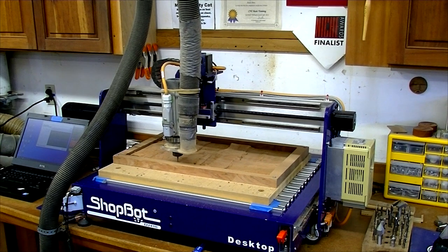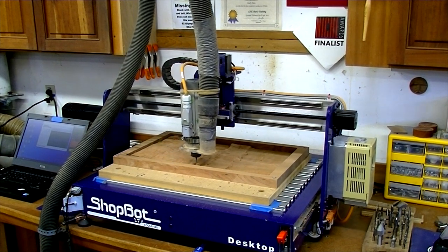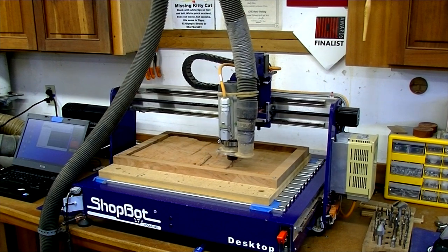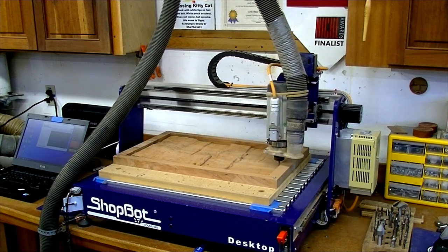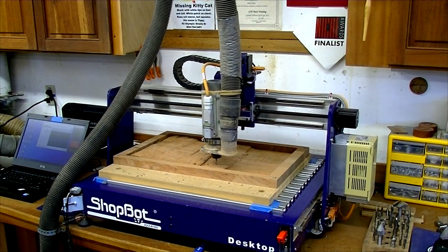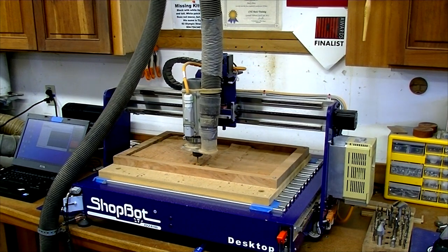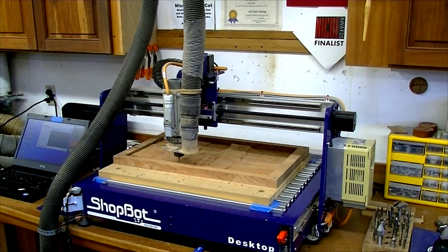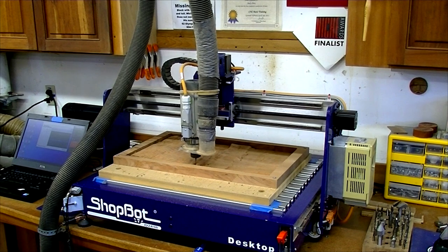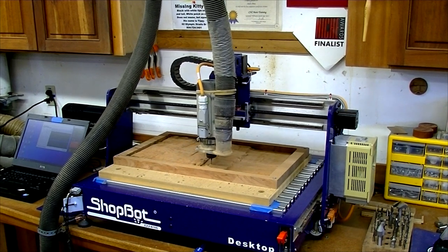Now I'm into the ball nose, 1/8 inch ball nose carving, so I'm really getting the image now. And I'm cutting it with about a 20-degree angle on the raster so I don't chip out any of the cherry. And because it's just making fine dust, I'm not using the dust boot and vacuum, just to save a little bit of electricity and a little bit of noise on my ears.